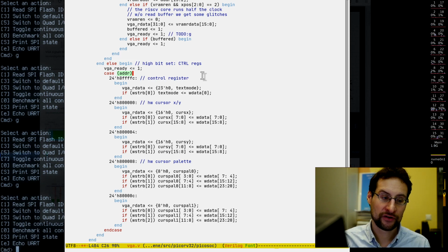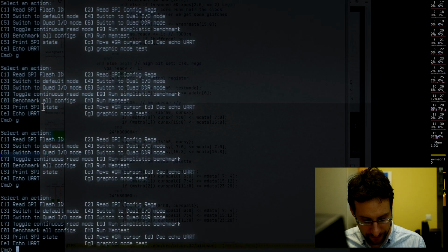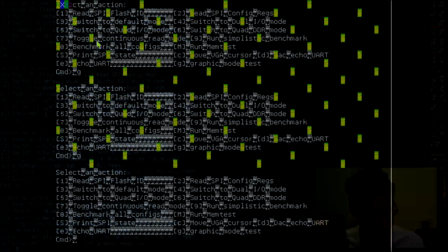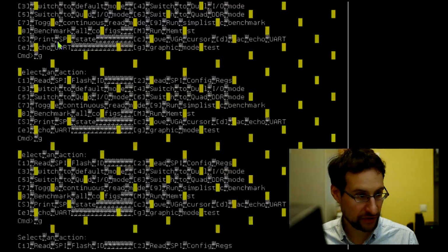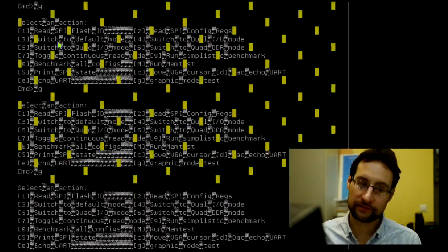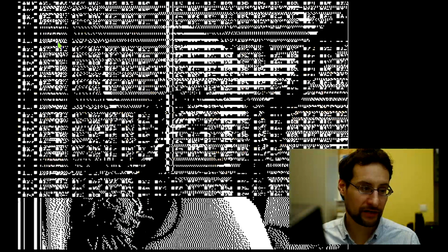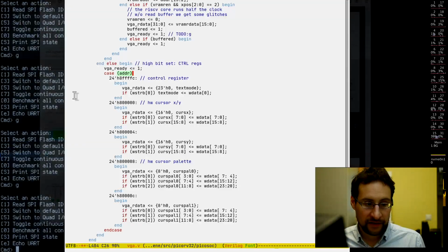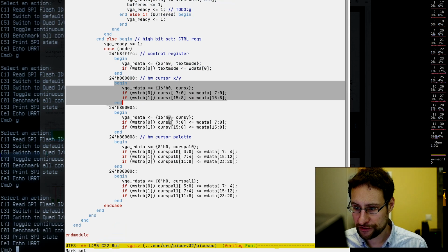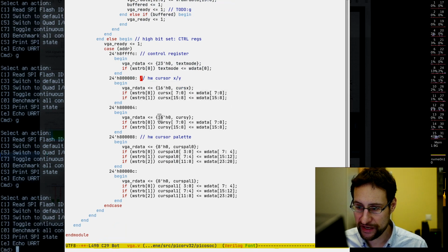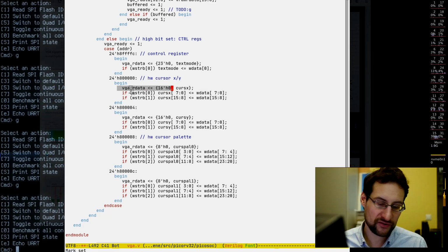start to output this video, graphic versus text mode here. As soon as we toggle, it's just like next pixel clock, it's like here, it's there. And then we have mostly writing for hardware cursor, and so hardware cursor X and Y, as you see, super easy assignments here, reading and writing supported.